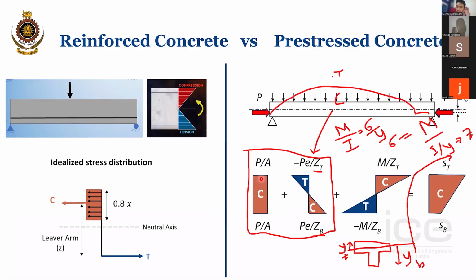So you can see, if it is not for the pre-stress, you would have only this one. Now with the pre-stress, you have another two components as well. So if you take the resultant here, compression, a small tension and a higher compression. So this will be in compression, definitely. Bottom part, this is again a compression, a small compression and a larger tension,